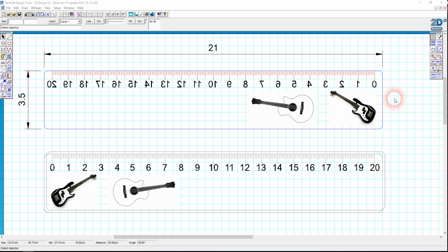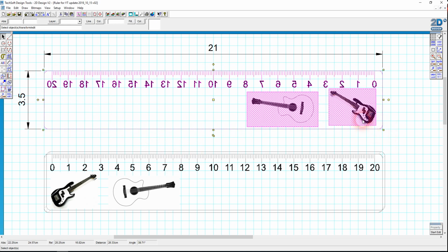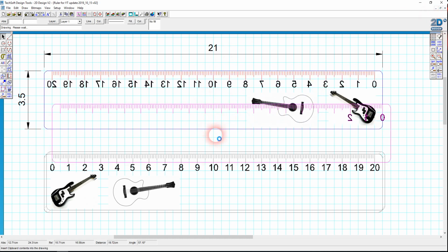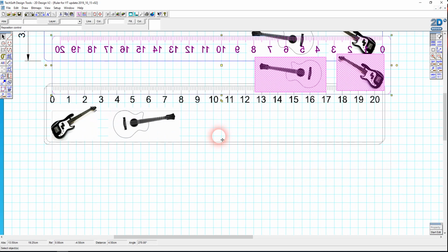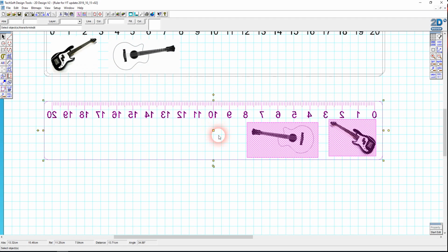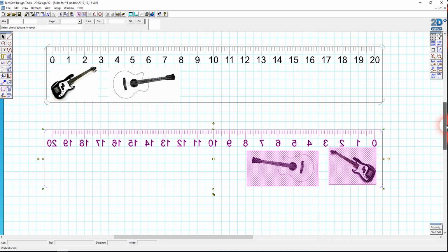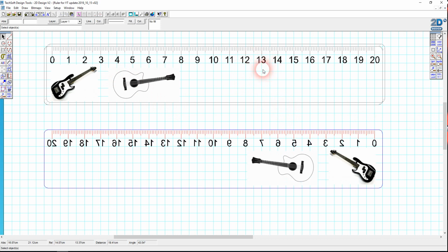Anyway, I want to put it back to normal, because this is supposed to be a 3D representation of the ruler as it will finally look. So let's select all of this. In fact, the first thing I'm going to do is copy it. I've got grid lock turned on here, Control C, Control V, and I'm going to bring this down, and maybe scroll down here so I can place it at this location and make sure I can still see the design above.